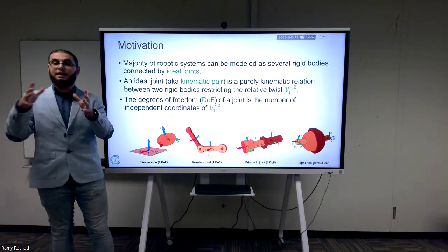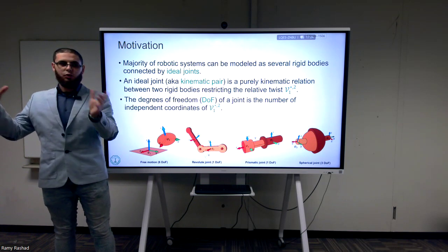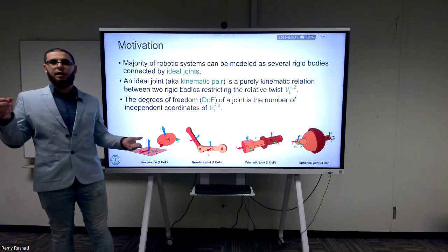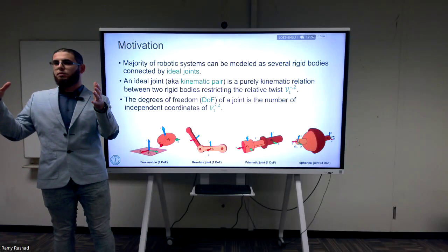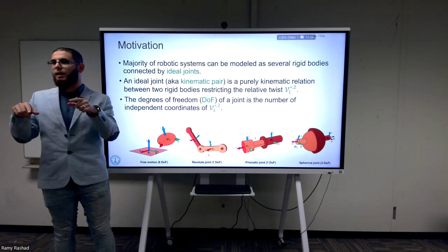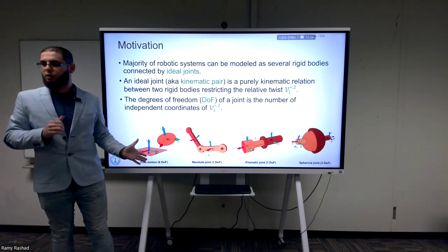And these 6 numbers, we describe them by how many numbers? So this is the 6 degrees of freedom. How many numbers do we describe this relative pose? 16, exactly. So we have a 4x4 matrix. Again, it has a very special structure such that it corresponds to rigid body motion.